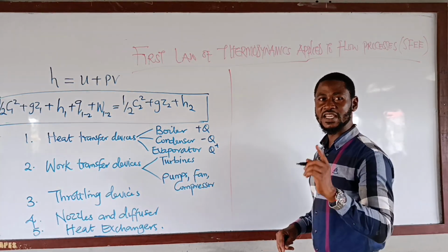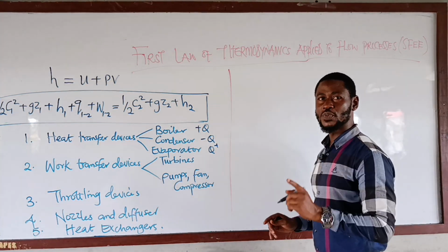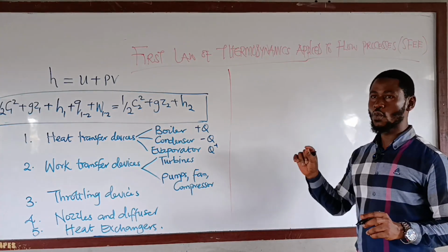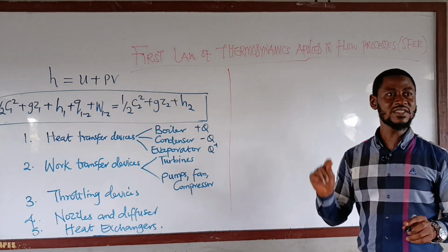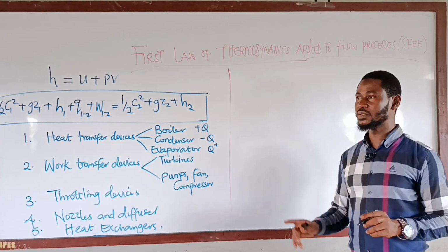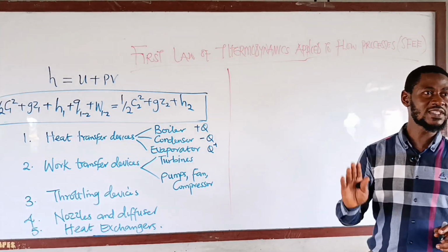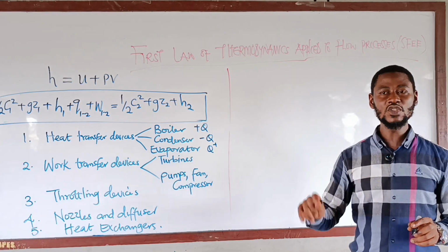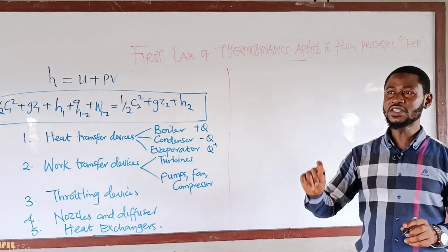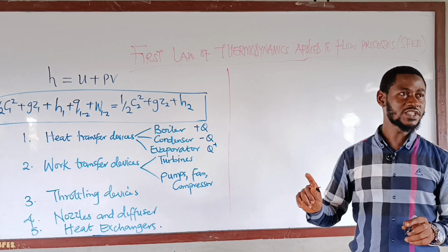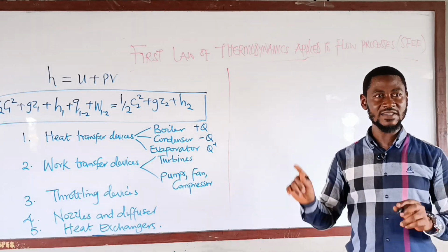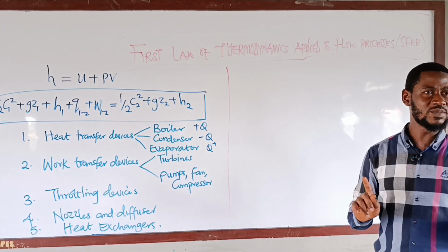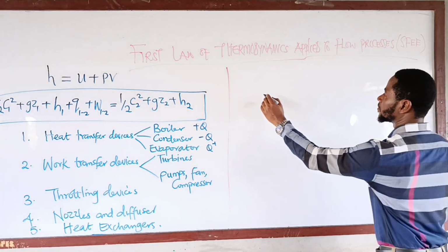The turbine is taken as work output, which is positive. The pumps, fans, and compressors are taken as work input. Having said this, we have done all this in sign convention, in which work input is negative, work output is positive, heat input is positive, and heat output is negative. So now, let's look at a simple power plant arrangement in analyzing this.